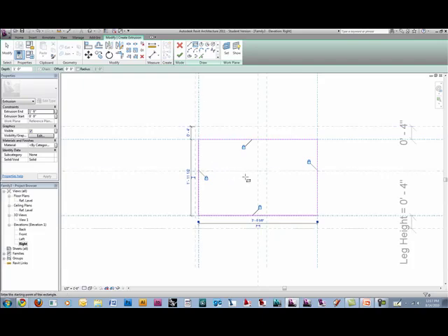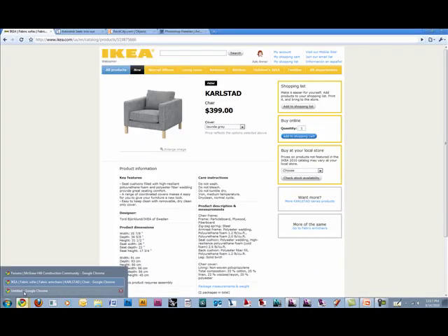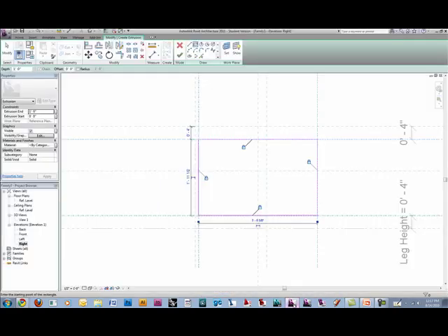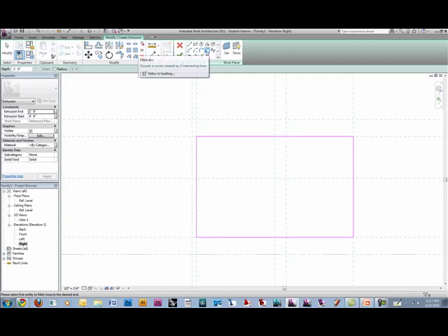No big deal. Alright, so the reason I did it in the right view is because if we go back and look at this, let's look at the actual picture. See the roundovers on the chair? We don't want sharp edges, we want those roundovers. So I'm going to use the fillet. That's this little button right here. Pretty sweet tool. Click here and here. You click the 2 lines you're trying to arc, basically.